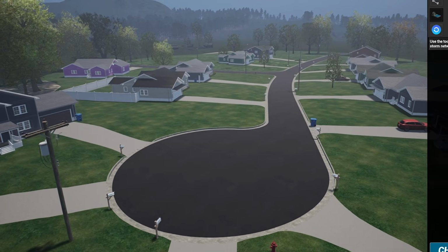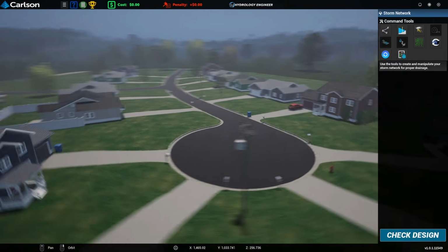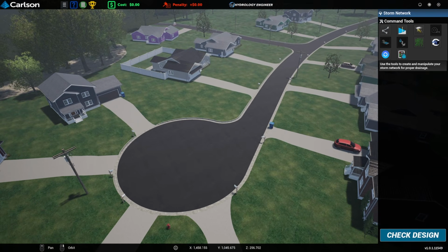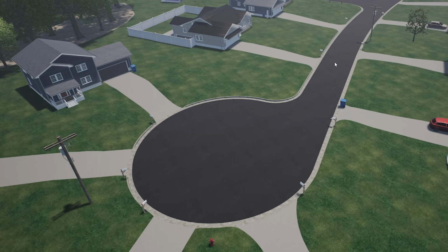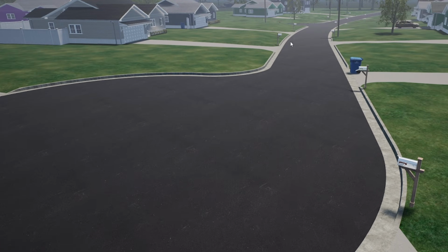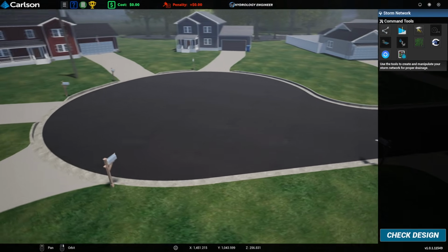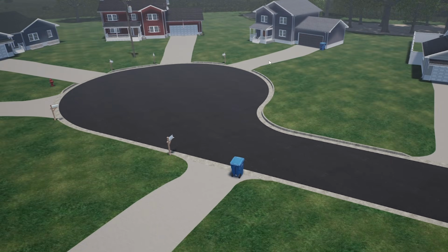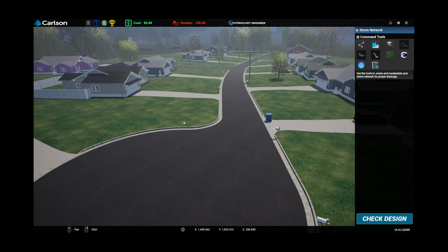It's worth noting that in real life, you wouldn't build the road and then come back and build the drainage. Whilst this does look realistic, it's not meant to be real. It is still meant to be a computer visualization before we actually go to site and build all this stuff, because generally the drainage actually gets built first. That's because the drainage is under the ground, so you lay your pipes first and then you come back and put your road on top, so that when it does rain, your road has somewhere to drain to. Whilst it's the thing that you design last, because obviously you need to know what's contributing towards your drainage in terms of hard areas, soft areas, that sort of stuff, it's the first thing that gets built. So no pressure on us drainage engineers.